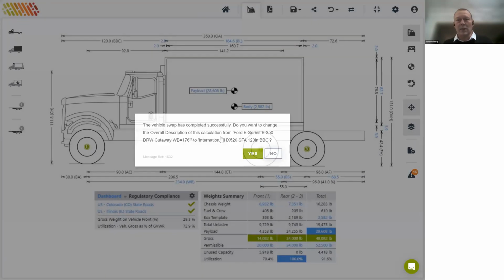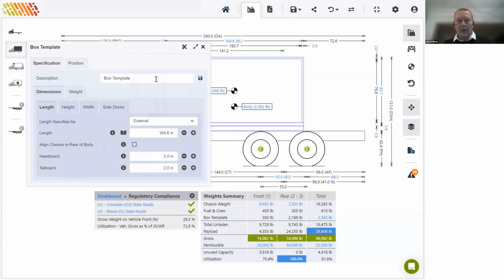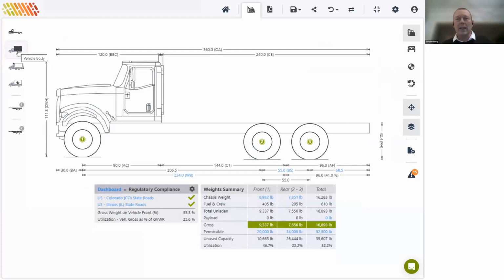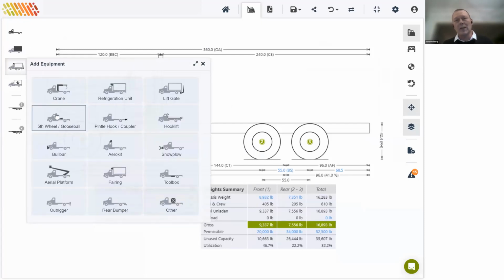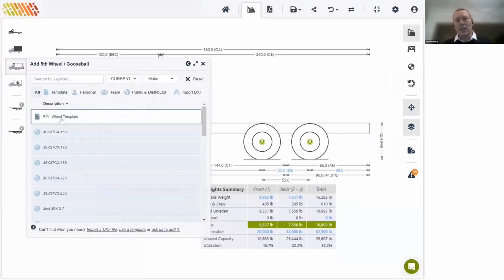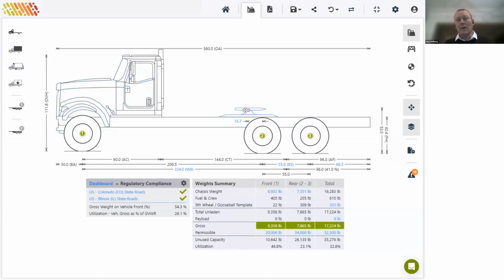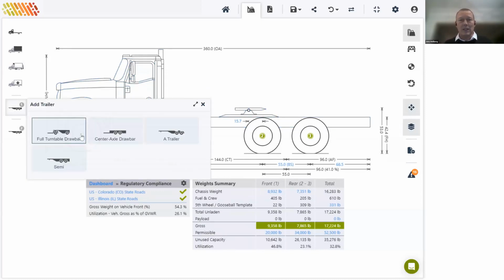Okay, thanks for that question. There's another question around, is there a limitation of how far behind an axle a fifth wheel can be placed? Specifically, we have an equipment truck pulling a supply trailer and want it to be 8 inches behind the axle. As far as I know, there isn't a limitation in our software as long as it's attached to the chassis. Sarika is just demonstrating it there.